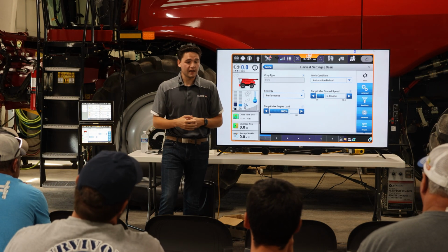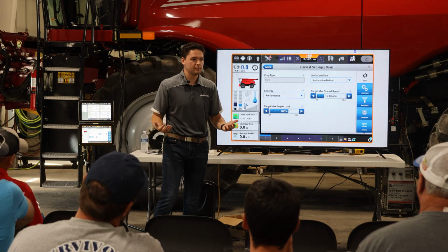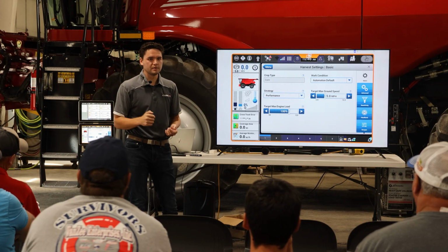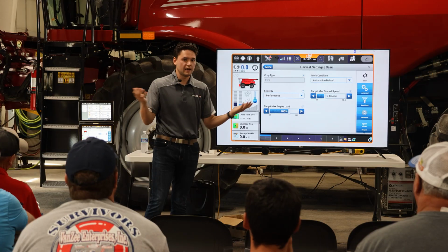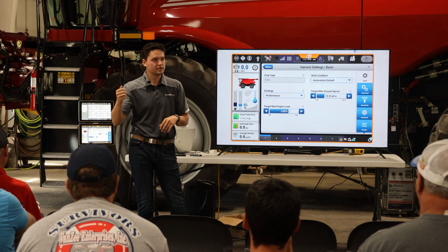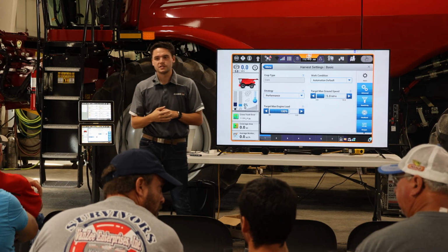So I typically see that a lot, and it's just simply because we didn't even know we were calibrating. We had no idea we were doing it because I had no idea there was a difference in the operation of feed rate from pressing it momentarily to pressing and holding it. I didn't know, and that's okay. That's what we're explaining now: pressing and holding starts a calibration sequence which will change its target point.